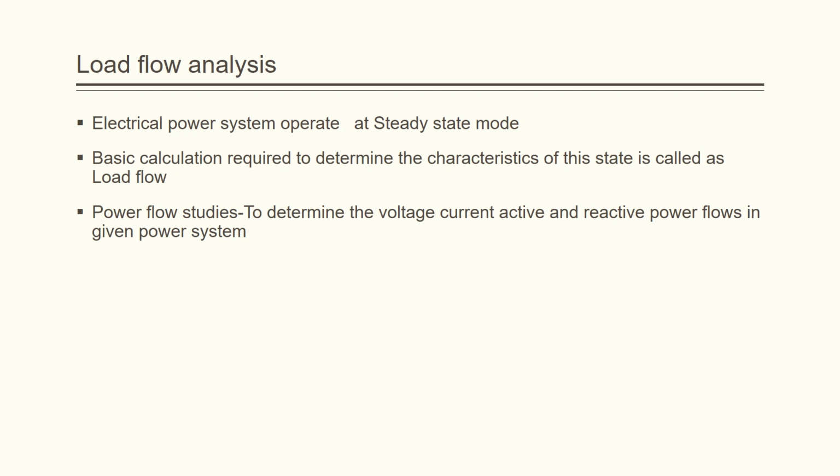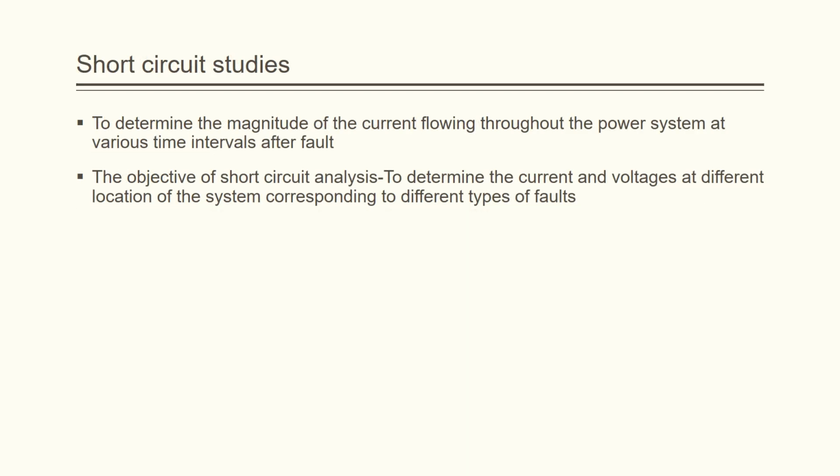Load flow analysis. Electric power systems operate in steady state mode. The basic calculation required to determine the characteristics of this state is called load flow. Power flow studies determine the voltage, current, active and reactive power flows in a given power system. Short circuit studies determine the magnitude of current flowing throughout the power system at various time intervals after a fault. The objective of short circuit analysis is to determine the current and voltage at various locations of the system corresponding to different types of faults.